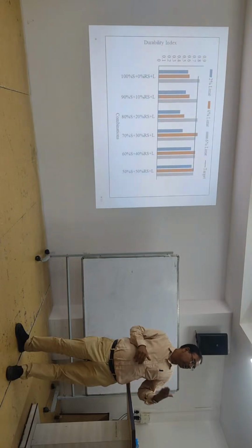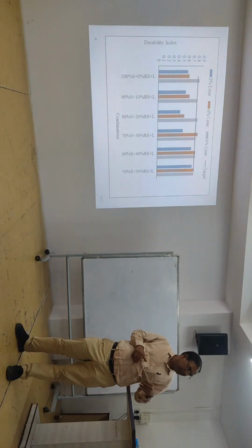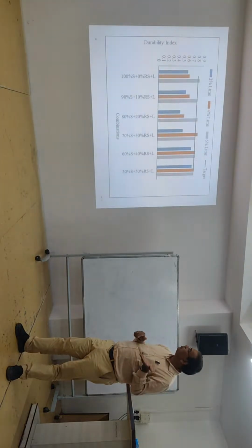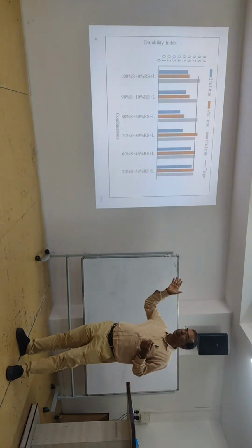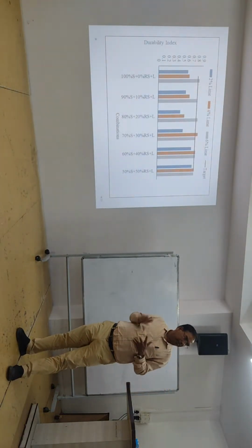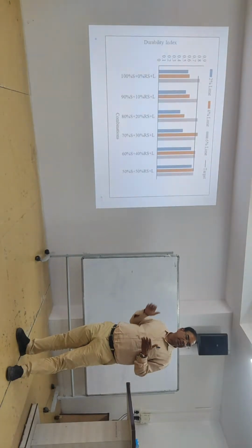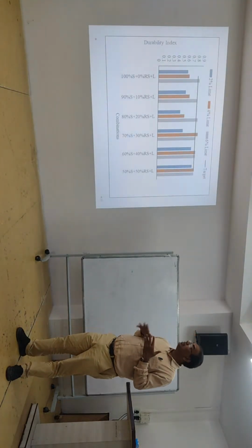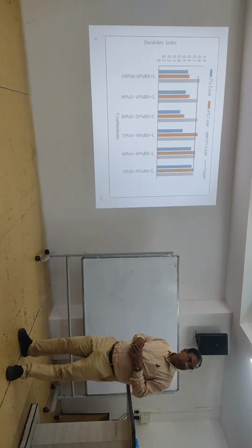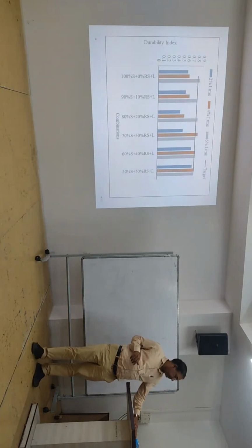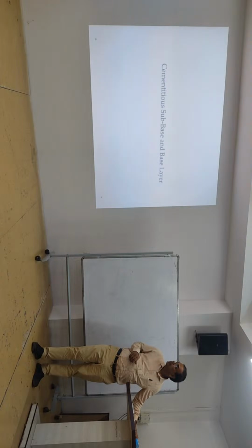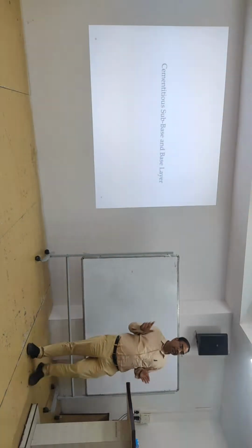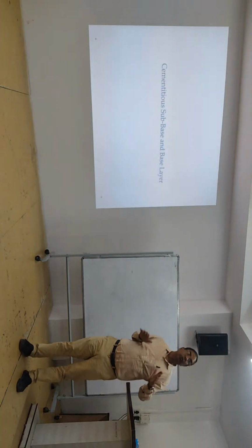The test is like putting in the water, then coming back, removing, and again putting in the water. So we get good durability also. The third quality, after CBR and UCS, is durability, and it is also passing. So with your sand, these are the three basics. This is the best first layer of the road construction.